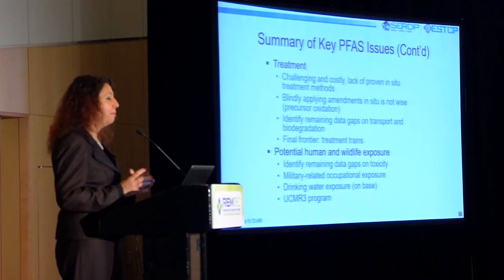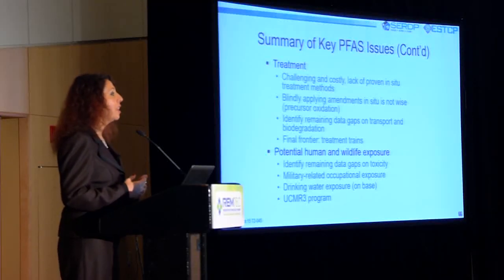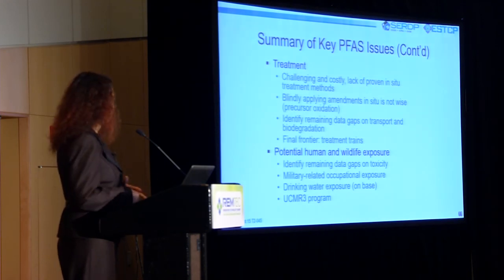As far as treatment, PFAS is a very stable compound that can make treatment challenging and costly. There is no evidence of in-situ treatment technologies that can holistically address the PFAS issue as of yet. Blindly applying amendments is not wise because of the precursor issues, so we advise caution. There are remaining data gaps on transport and biodegradation that SERDP and ESTCP are trying to address. And then the final frontier is reliance on treatment trains as we start doing more RIs.